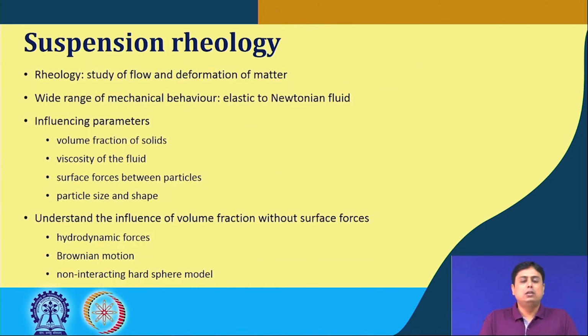Now, if we go into the suspension rheology, we are talking about its density, viscosity and all this. Rheology is the area where we study the flow and the deformation of matter. It comprises a wide range of mechanical behavior, from the elastic behavior, which follows Hooke's law, to the whole range of Newtonian fluid.